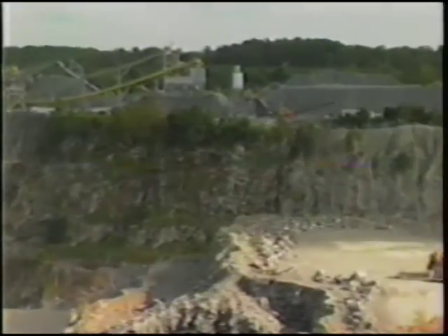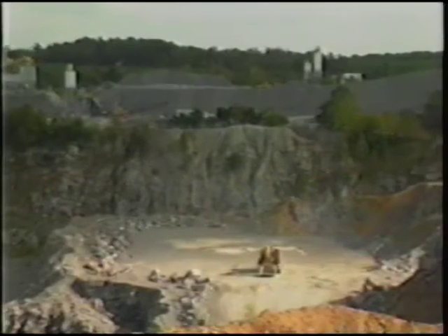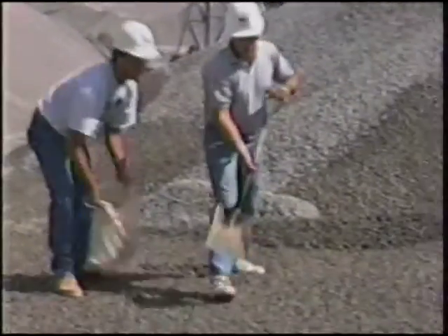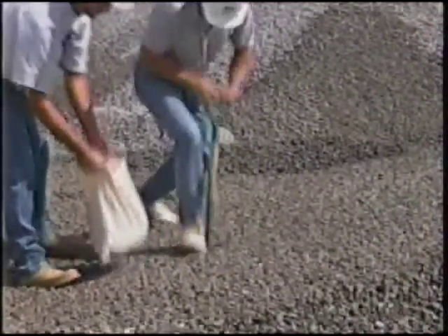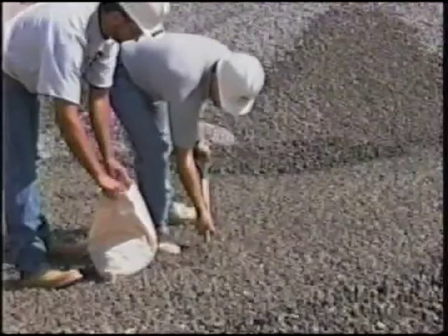All workers should keep a close watch for any changes in the aggregate material. One of the most obvious changes is an alteration in product color. Workers should also watch for any sign of coating or other contamination. It's important to catch this before an entire stockpile is contaminated. Before the product is ready for final delivery, it must be inspected.